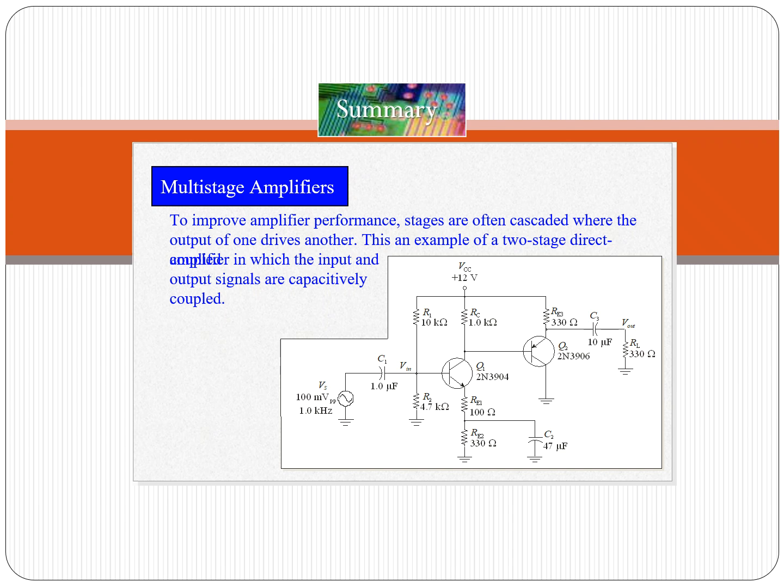So capacitive coupling, like we see here, blocks DC and allows only AC signals to pass. It's ideal for signal amplification without DC offset interference. And again, the big idea is that multi-stage amplifiers let you stack strengths using different topologies, like a common emitter for gain, followed by a common collector for buffering, or even combining Darlington, Sziklai, and differential designs all into one big powerhouse. And that's it for this slide. I will see you on the last slide.